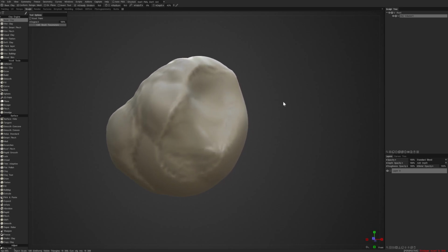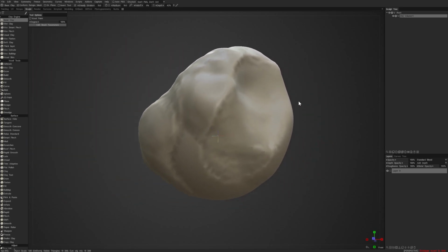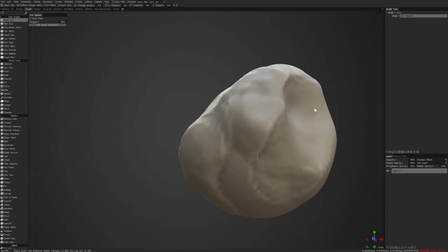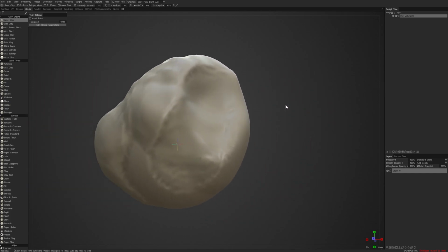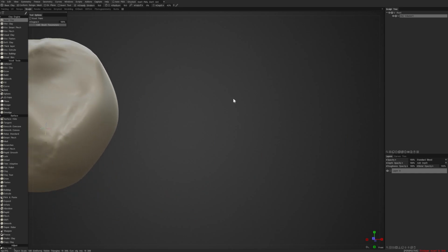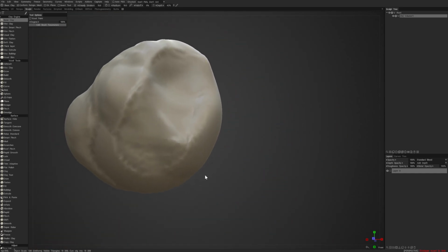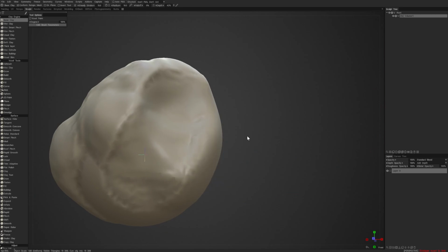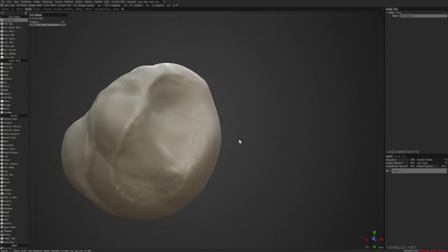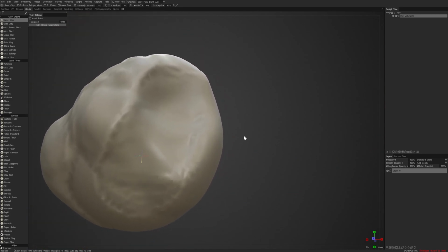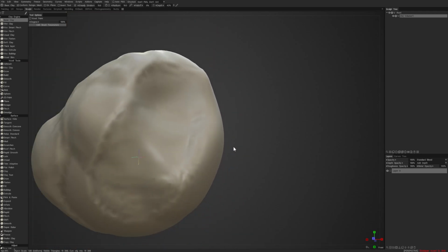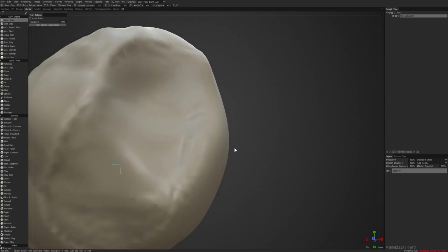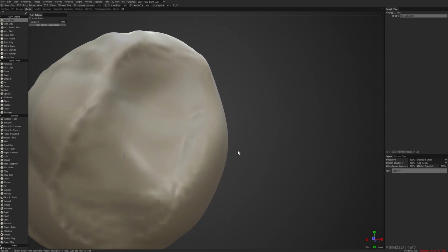Then I'm also pressing the stylus button, which is the equivalent of a right mouse button click. So left and right together will give me this panning effect, allowing me to move my object like so. Right mouse by itself, hovering above the screen, not touching down, left and right allows me to zoom in and zoom out. Again, this is off my mesh.